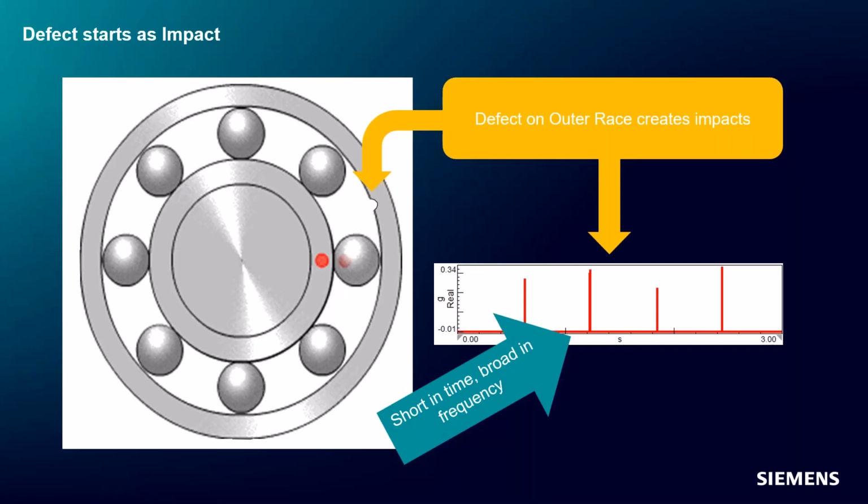And so a bunch of small impacts, and an impact short in time duration, but in the frequency domain, what does that look like, Steph? A bunch of frequencies. Yeah, very broad in frequency. And that is part of the reason we can see a difference there at the very high frequency range of 30,000 up to 35,000 hertz. And we don't see it anywhere else because these impacts are pretty small compared to the general vibration going on.